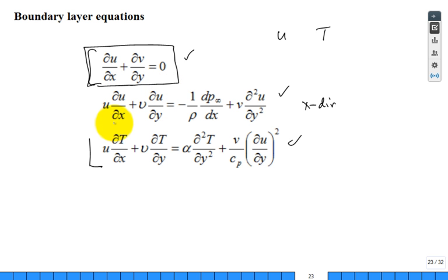All right. Well, if you can understand this equation, you just look at it. What is this? Advection of energy or internal energy. I know that they've taken the specific heat out. And what does this look like? That looks just like this one. This was the law of viscosity, diffusion of momentum. This is Fourier's law, diffusion of heat or internal energy.